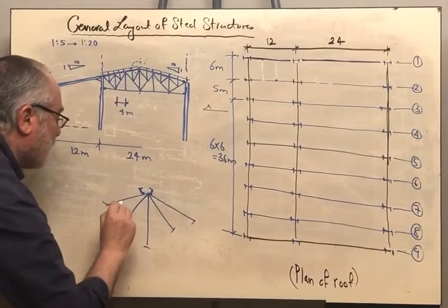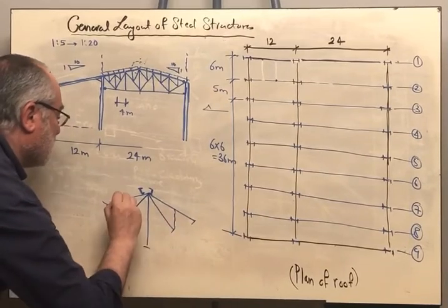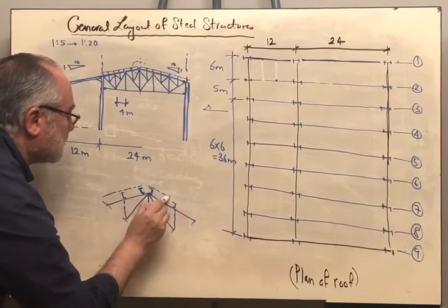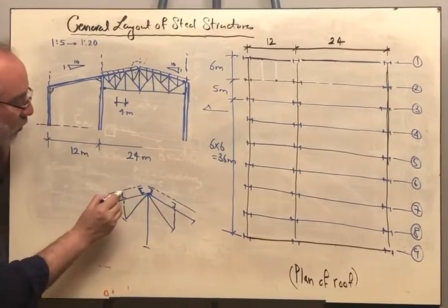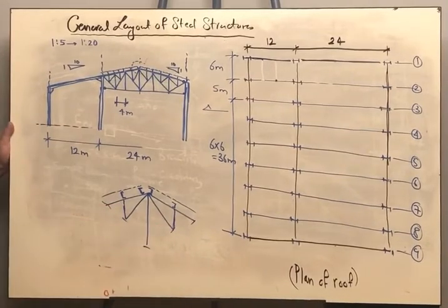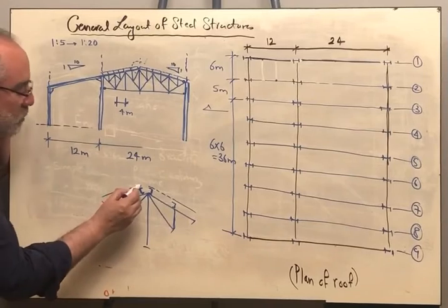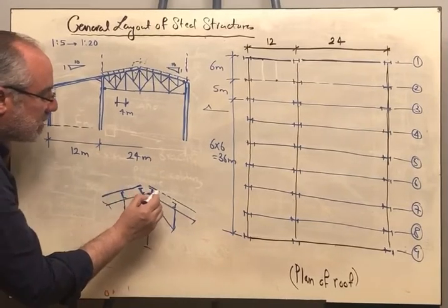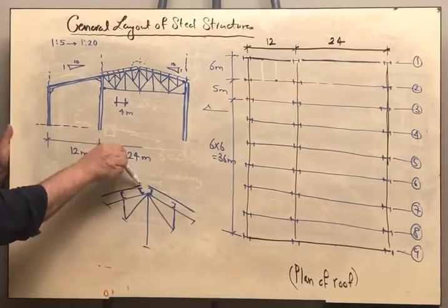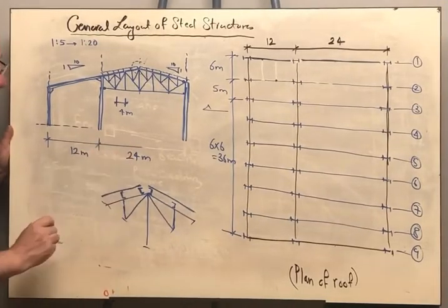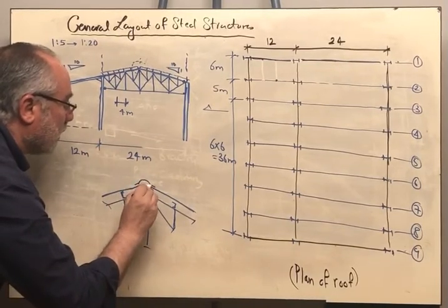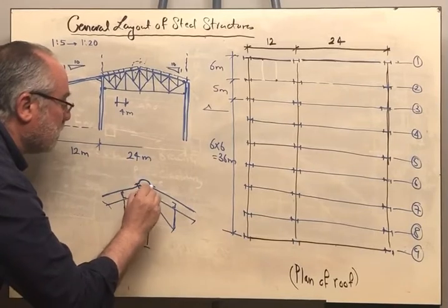And of course we are having purlins like this, and this is the cladding. The purlins are always located over the joint, as you know. Now this sheet and this sheet cannot be bent, and this part is void. Dust or rainwater can enter from there. So there should be an accessory that will close this part, as you have seen in our previous lectures.